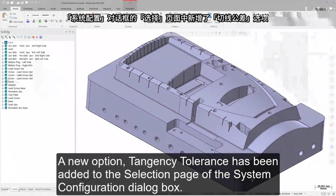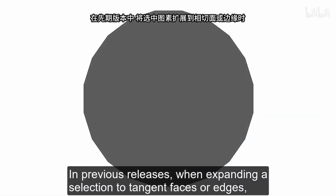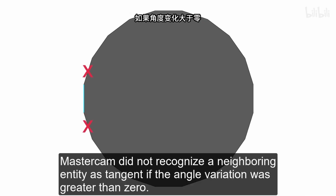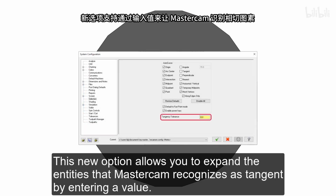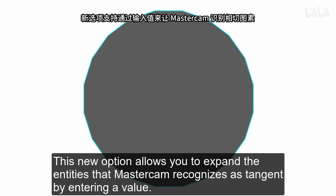A new option, Tangency Tolerance, has been added to the selection page of the System Configuration dialog box. In previous releases, when expanding a selection to tangent faces or edges, the tolerance was limited to neighboring entities that aligned with the selected entity. Mastercam did not recognize a neighboring entity as tangent if the angle variation was greater than 0. This new option allows you to expand the entities that Mastercam recognizes as tangent by entering a value.